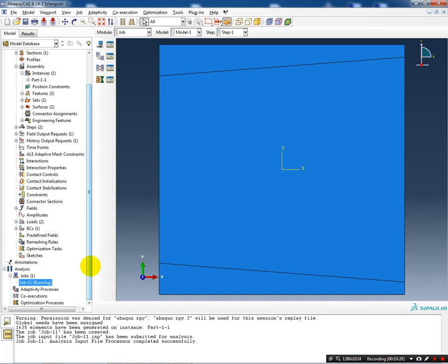Running. The preprocessor has completed successfully, so that's good. The actual job is running. And if we don't run out of increments, or we don't have too much, it should work out. Okay, so it said it completed successfully. Sometimes you will see, if you don't have enough increments specified, remember where I changed that 100 to 1000, it will bail out on you and stop. So you have to go back and try again.